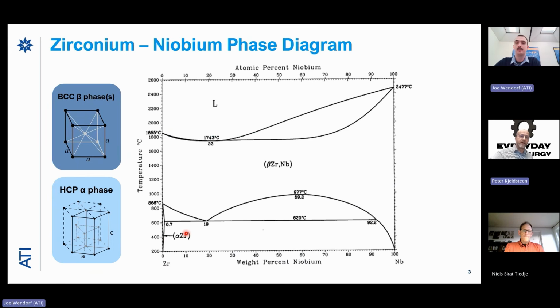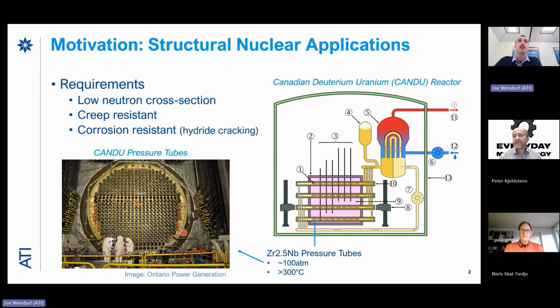What is the designed lifetime of such a machine? So there's a new generation of CANDU design where they're trying to increase this, but currently these reactors are designed for the pressure tubes to last about 15 to 20 years, and then they'll do a really long maintenance period where they replace all the pressure tubes. It's called a retube, and then it'll run for another 15 to 20 years.